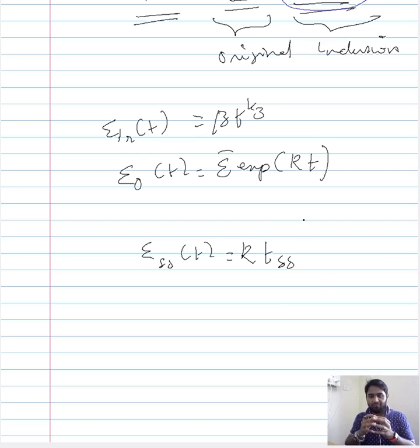So, what we have is a term K that represents a definite change in the dimension of the material during a period of time, and when you multiply that definite change in strain of the material during the period of time by the overall period of time, then you end up with the overall strain during steady state condition. So, this time is for the steady state condition.